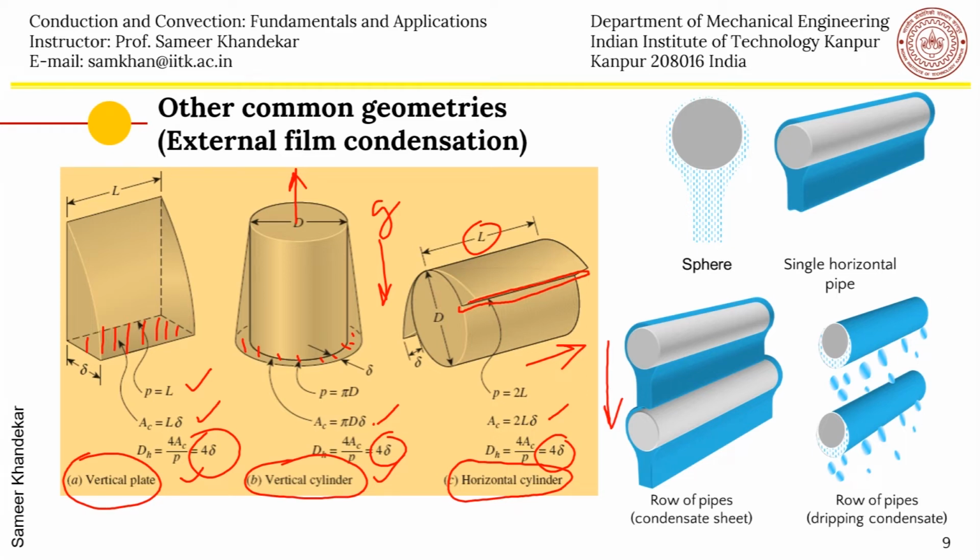And this is also helpful because depending on the distance and the rate of condensation, you may have droplets which are falling down, and they are made use of because these falling droplets will disturb the boundary layer at the lower position. Similarly, more and more liquid will keep falling down in this heat exchanger, and you will eventually see that the heat transfer actually increases because of this continuous bombardment of tiny droplets or liquid films falling down from the top cylinder to the bottom cylinder.